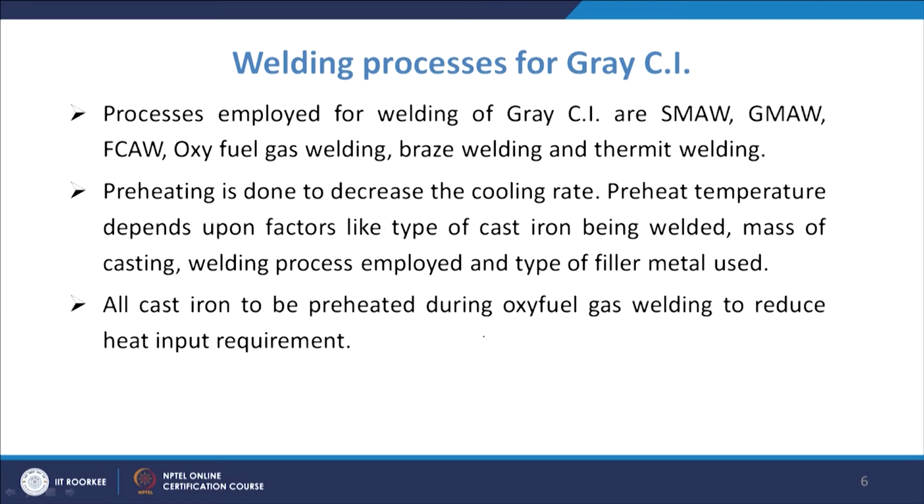Then you have the preheating. So, preheating we are doing to decrease the cooling rate. It will depend upon factors like type of cast iron being welded, mass of casting, welding process employed and type of filler used. So, these points are to be taken into account.